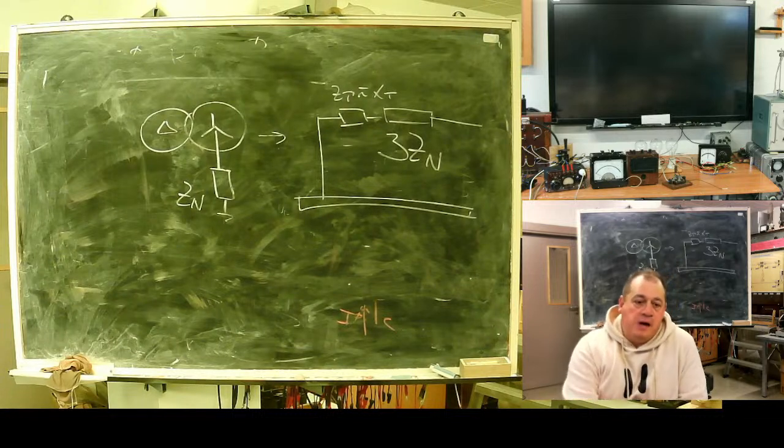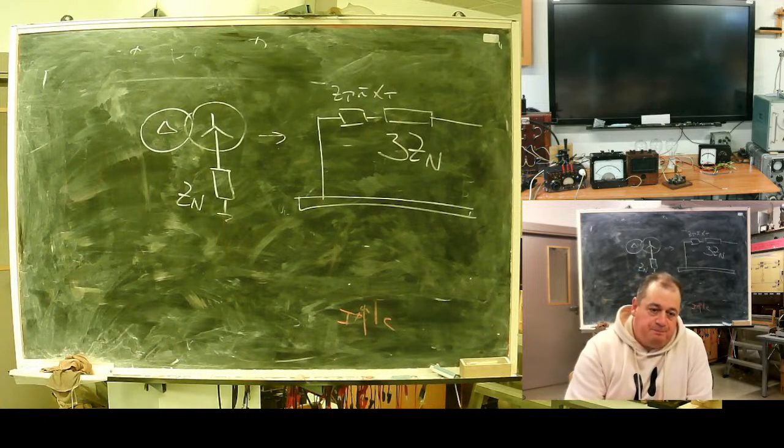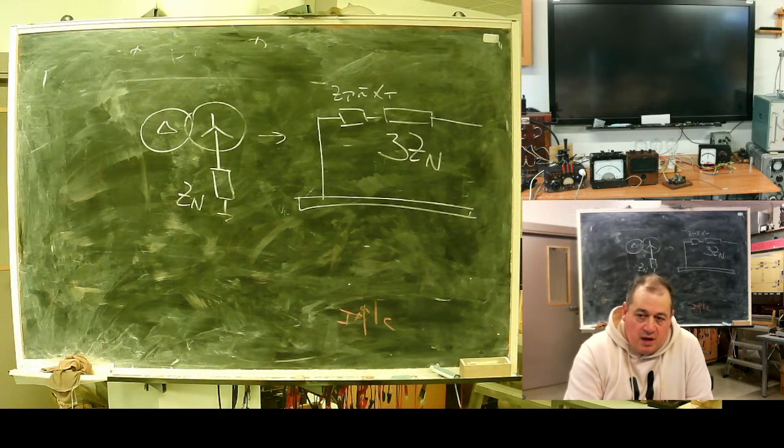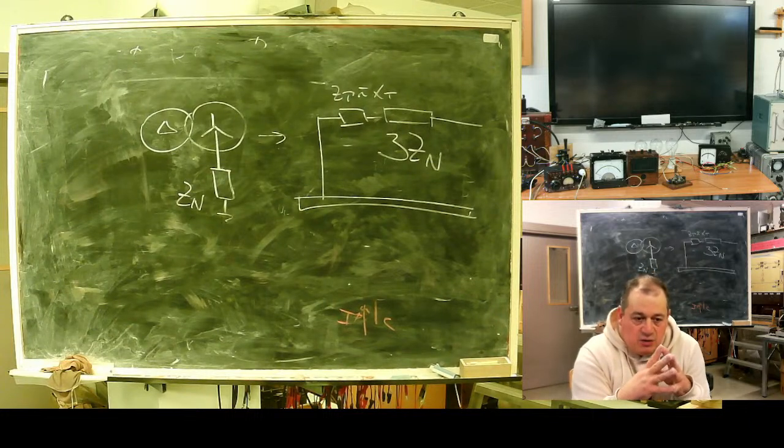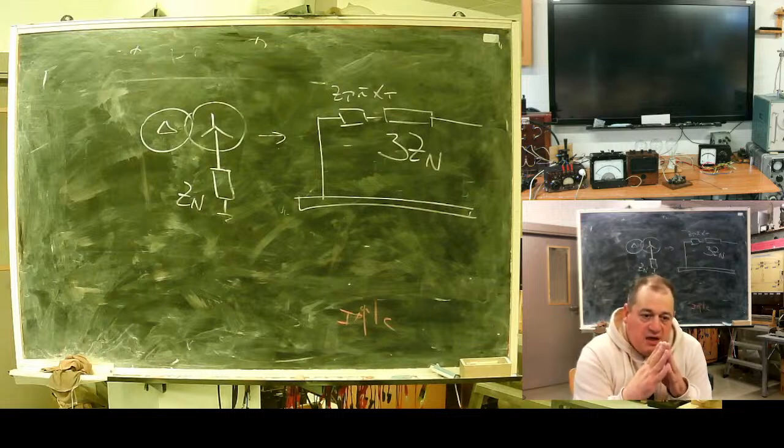What else? About power lines. First, overhead lines. Okay, one step back. Inductive reactance of the line is dependent on the distance between wires. The closer the wires, the smaller the reactance of the line.